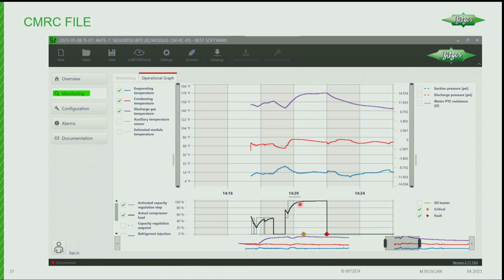What happens here is you can see that when the compressor shuts off, the blue line, your suction pressure and temperature, goes up, obviously. On a rack system, it might not go up so dramatically because you have other compressors running, but the discharge pressure goes down and your discharge temperature goes down. All makes sense. When the compressor turns on, we have our suction pressure start to come down, our discharge pressure start to go up, and our discharge temperature start to go up, which all makes sense.